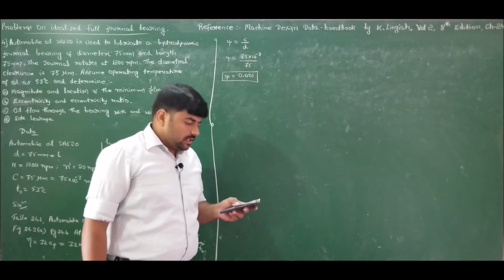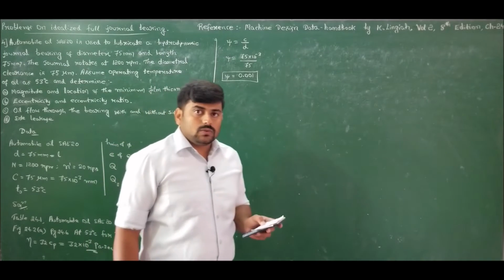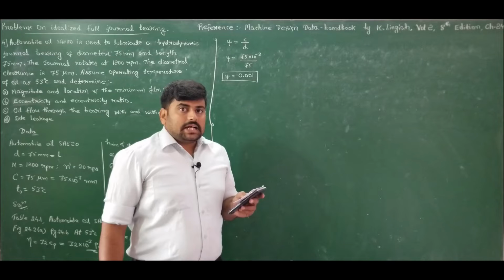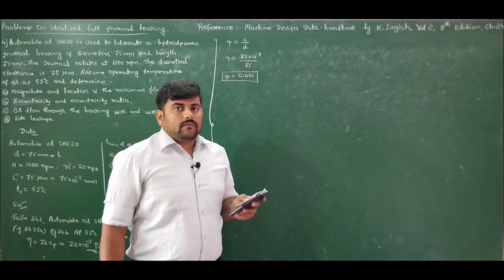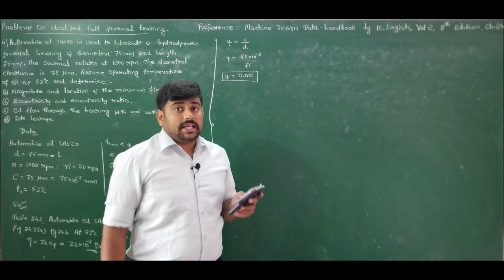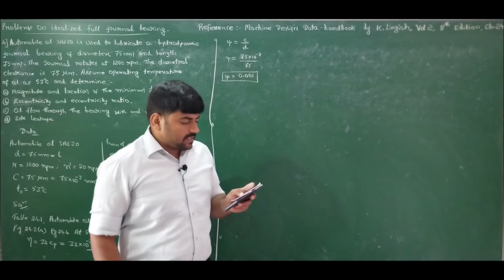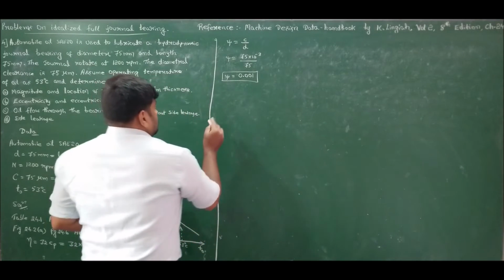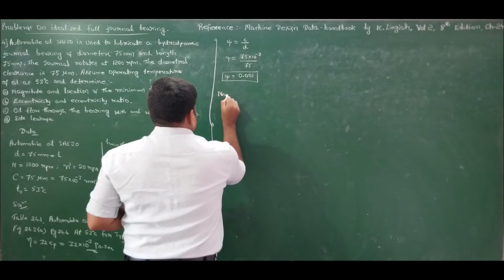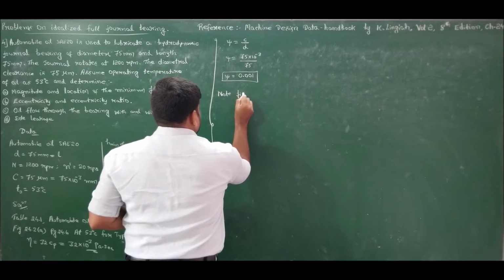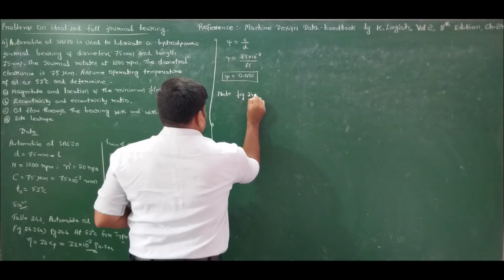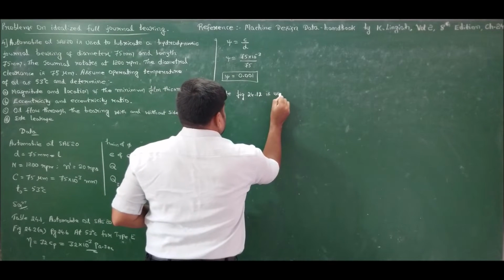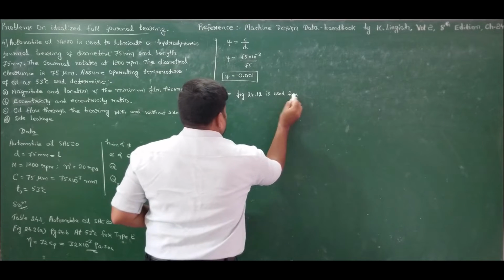Usually we use figure 24.12 to determine film thickness variable delta, using which we can find minimum film thickness if there is no side leakage. If side leakage is specified, we should refer to figure 24.24. Note, figure 24.12 is used for no side leakage.